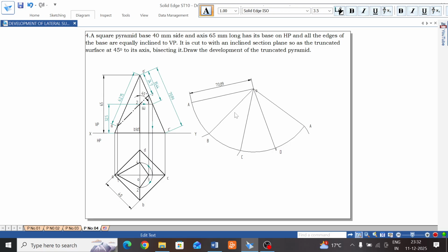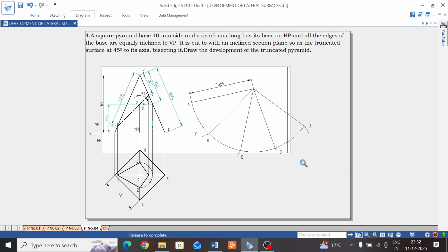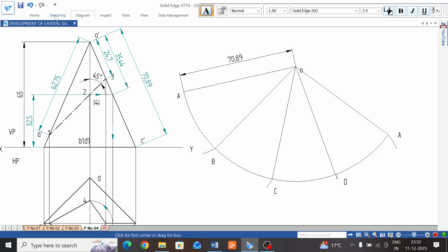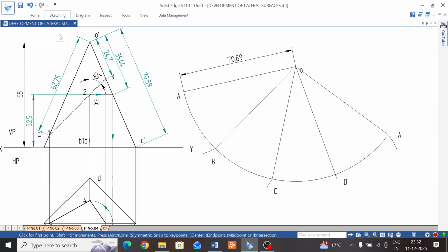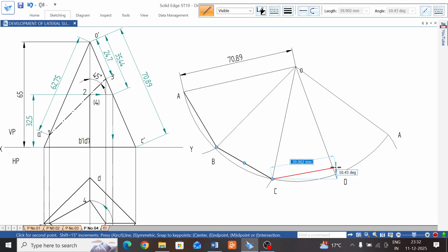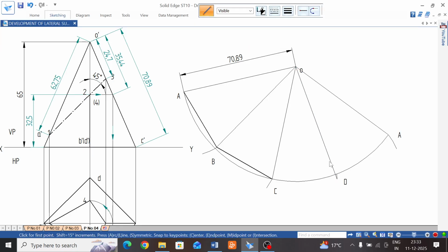Now, zoom this much, it's a pyramid section. Now select the thick line, and join those by A to B thick, B to C thick, C to D end point. Here, end point only, how to select. If the line is not proper, this line, delete it.